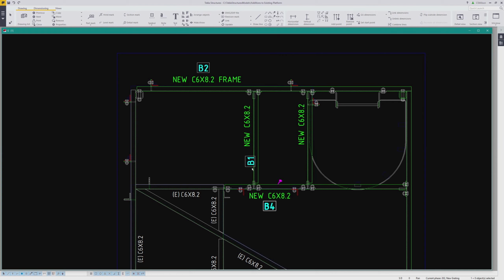The note can be moved parallel along the direction that was set and is locked at a fixed distance. However, you can move the note by selecting it and then holding down the Shift key and left clicking on it to drag it to the desired location. I'll show it again in real time.